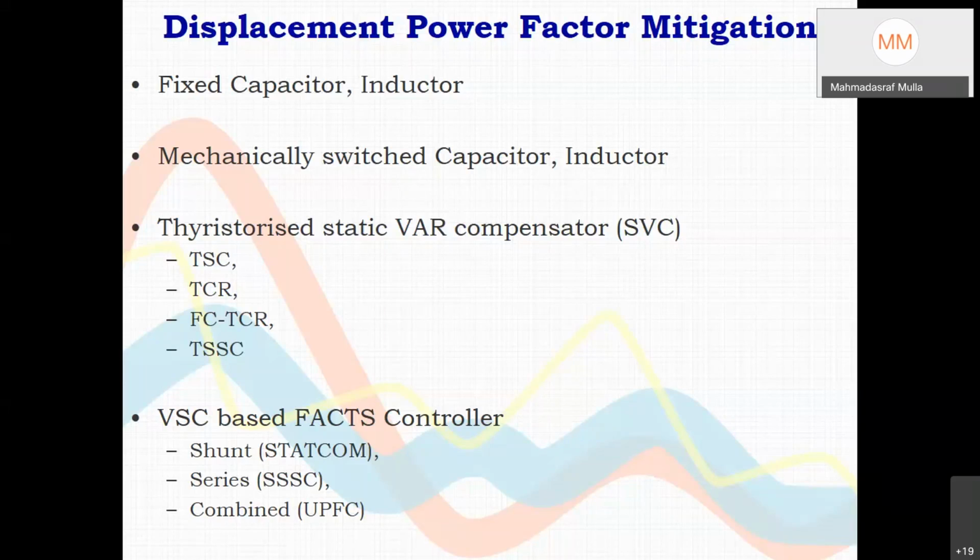So large number of capacitors, big size. Similarly, if there is a capacitive load, then you will require a big reactor. Then afterwards, thyristor will come into picture to connect and disconnect that. Now, if you come down to SVC based FACTS controller, you are exchanging reactive energy at 10 kilohertz.